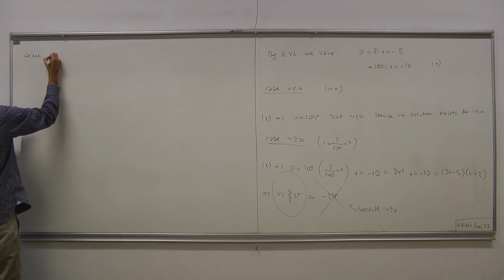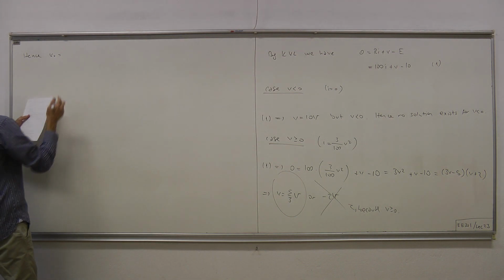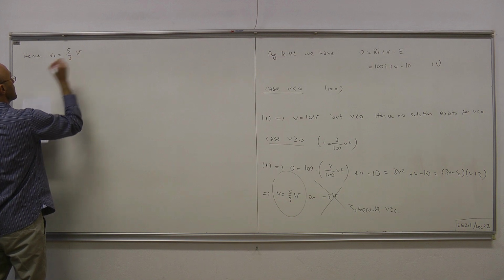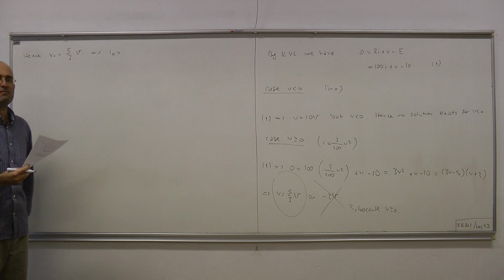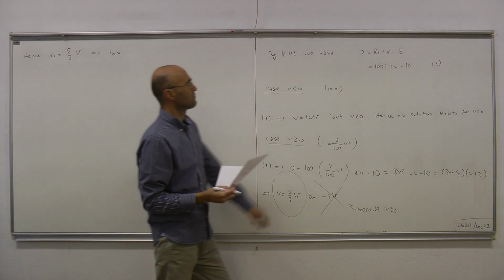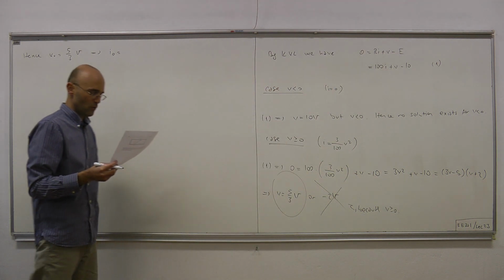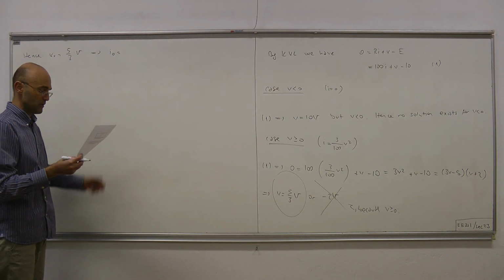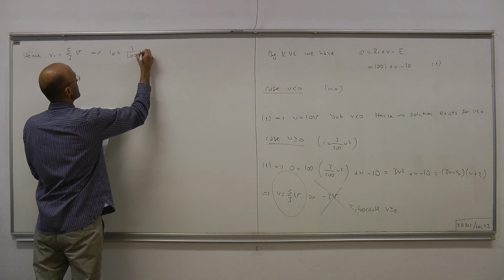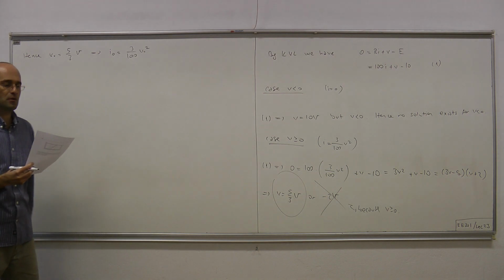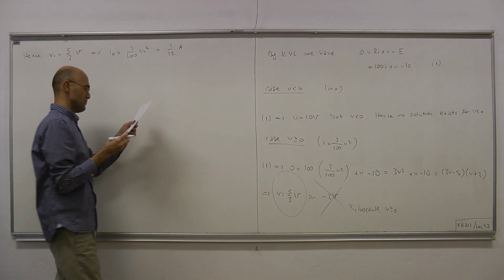So finally, the operating point must have the voltage V0 equals 5/3 volts. And then the current can be computed either using the load line or the terminal equation. They must both give the same answer. So let's use the terminal equation: 3/100 V0², which is 1/12 amps.